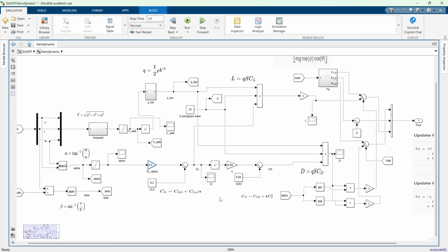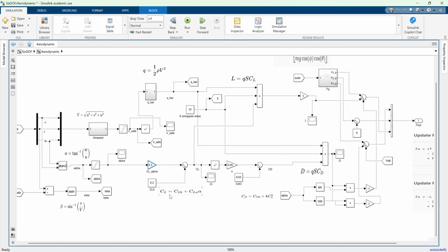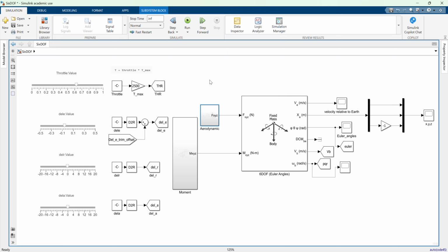And with high fidelity, it will be lookup tables, but not as a function of one parameter, alpha, for instance, but it will become a lookup table with a function of 3 or 4 different parameters. So again, giving you that CL example, you would be able to have a lookup table that will give you CL as a function of alpha, beta, Q, and multiple things like that. So that way you would be able to account for things like stall behavior, things like engine spool effects, and very minute effects like that, which will in a way help to increase the fidelity of your model.